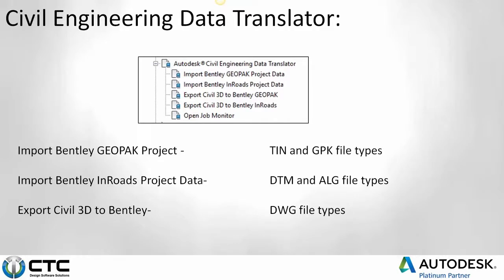So what used to be having to redraw something or having MicroStation just save it as a DGN and dumbing everything down and then bringing it back in, now I have the capabilities of bringing in a TIN, an alignment, a terrain model, and have it be built almost perfectly. Have I seen a surface come in 100% correct? No, but it's been 98% correct. There's always been just a little tweak here or there, but starting at 98%, then starting at 0% is still always better.